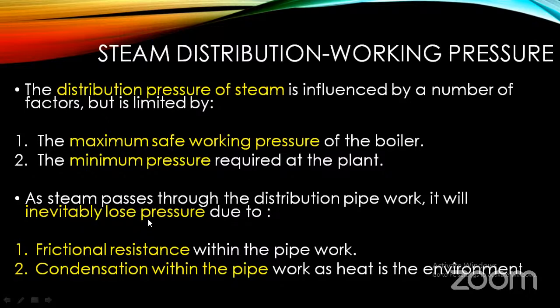The pipe work will have some pressure loss, again due to two main reasons. One is the frictional resistance occurring within the pipe work, and the other factor is the condensation that happens within the pipe as heat is lost to the environment.